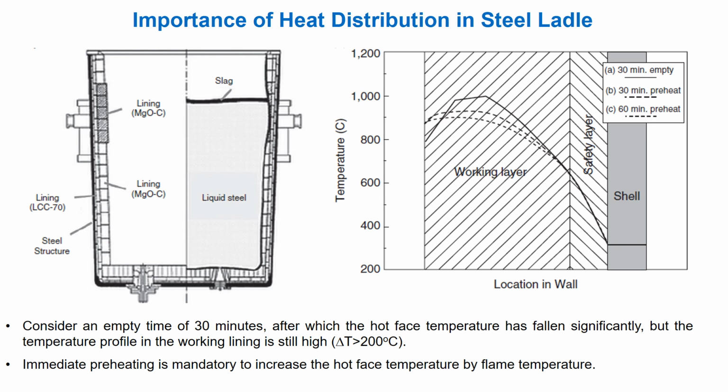Here, heat transfer mechanisms for raw material processing and refractory processing are already discussed. In this slide, a typical steel ladle lining consisting of metal, slag working zone magnesia carbon, backup LCC 70 and flow control refractories experiences heat transfer phenomena during different operational conditions. Uninterrupted operation without delaying ladle engagement is always challenging for the steel melting shop.